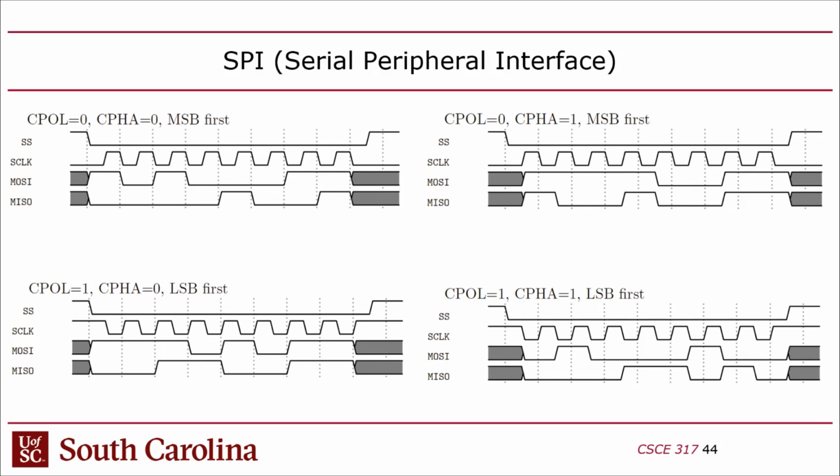Something else you never mentioned, but my friend showed me quite recently, is he's working with a device that uses SPI. The clock periods and the actual height of the clock can be a little bit garbage too. On a real device, sometimes the clock would only go a little bit high, and sometimes it would go really high. Oh yeah, because you've got losses. It doesn't matter how high it is as long as it finds the edge. I was like, yeah, this stream looks horrible versus those nice textbook ones.